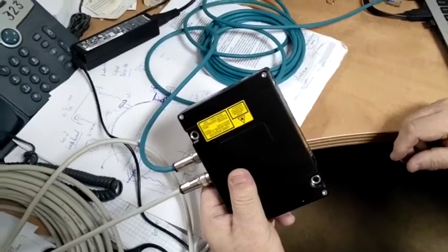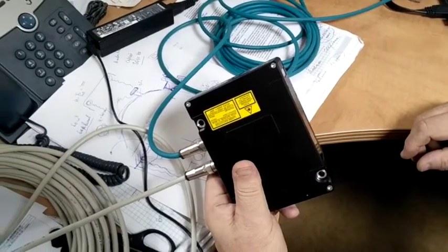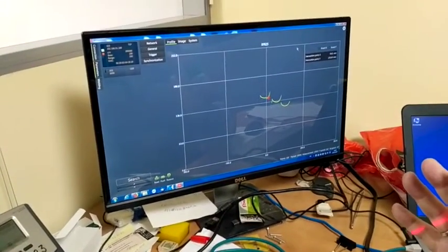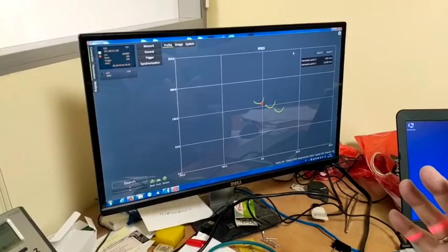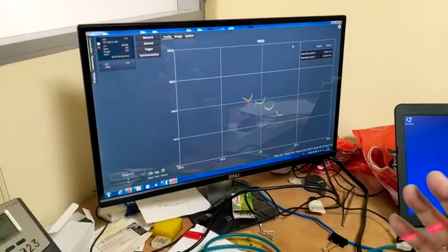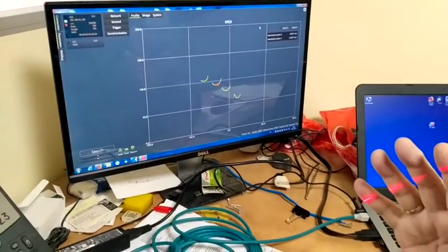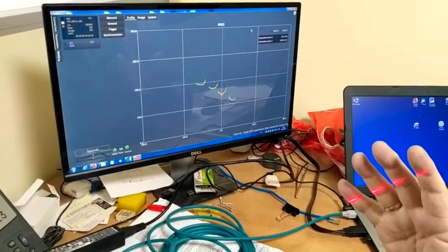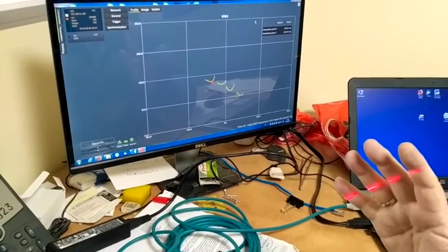One of the sensors' operation you can see on the screen. The key point of the sensor's work is that the sensor beam, spread in a line, is reflected from the measured surface and is focused on the sensor-sensitive matrix. And the sensor processor calculates the distance to each point of the laser line. Thus the geometrical profile of the object on which the laser beam falls is calculated.